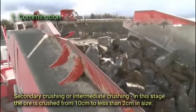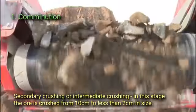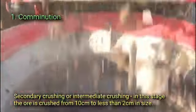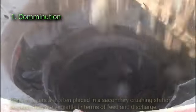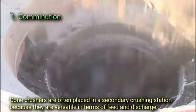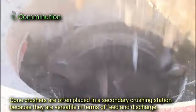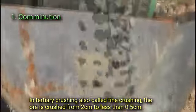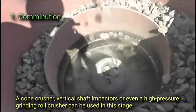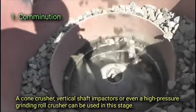Secondary crushing or intermediate crushing. In this stage, the ore is crushed from 10 centimeters to less than 2 centimeters in size. Cone crushers are often placed in a secondary crushing station because they are versatile in terms of feed and discharge. In tertiary crushing, also called fine crushing, the ore is crushed from 2 centimeters to less than 0.5 centimeters. A cone crusher, vertical shaft impactors, or even a high-pressure grinding roll crusher can be used in this stage.